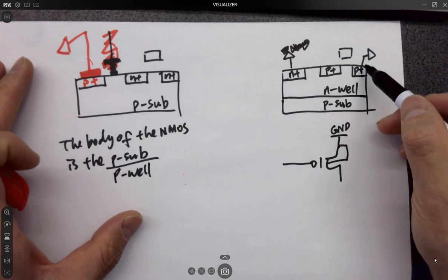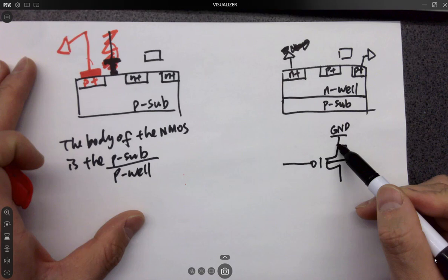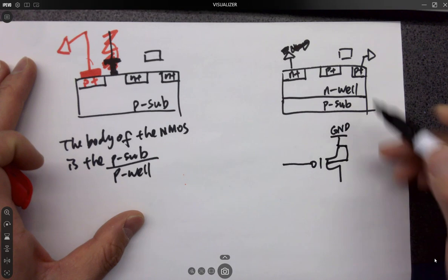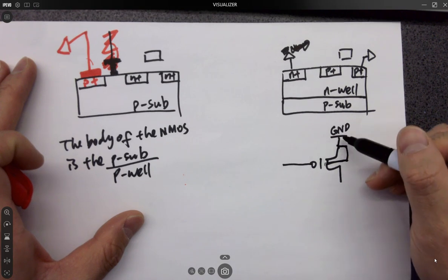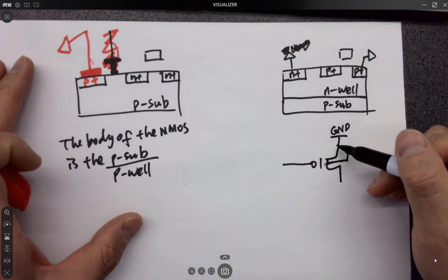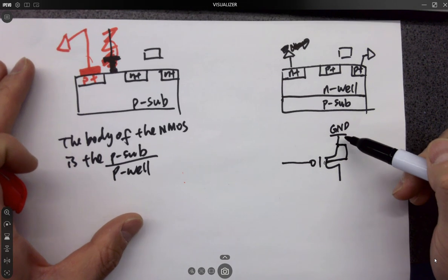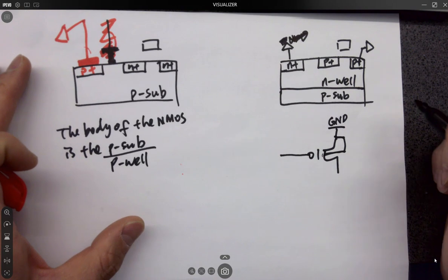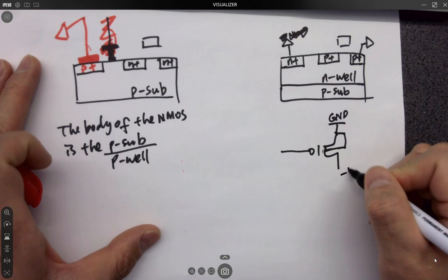You are supposed to short the body and the source to the highest potential of the circuit, because we just learned PMOS is good at passing ones, right? Why in the lab can we ground it? We use a negative voltage. Yeah, it was just a negative voltage, right?